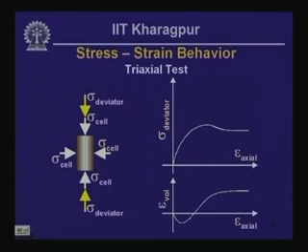So, we have got a deviatoric response in which we plot the deviator stress versus the axial strain, and then we have got a volumetric response in which we plot the volumetric strain versus axial strain. And if you recall, the summation of the strains on the three orthogonal coordinate directions is going to give you the volumetric strain.